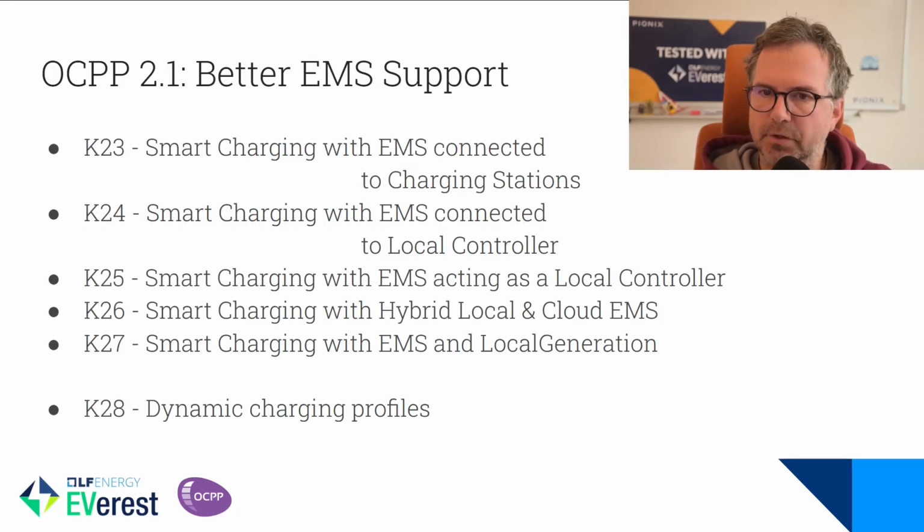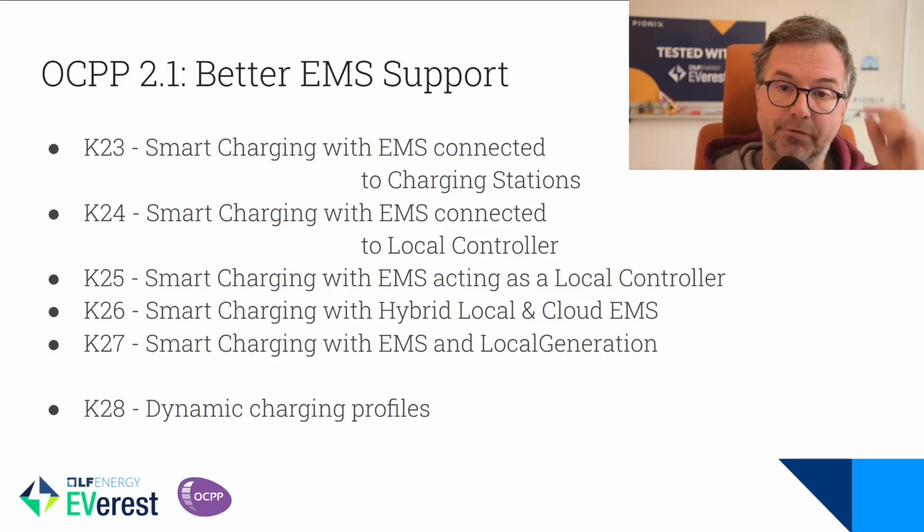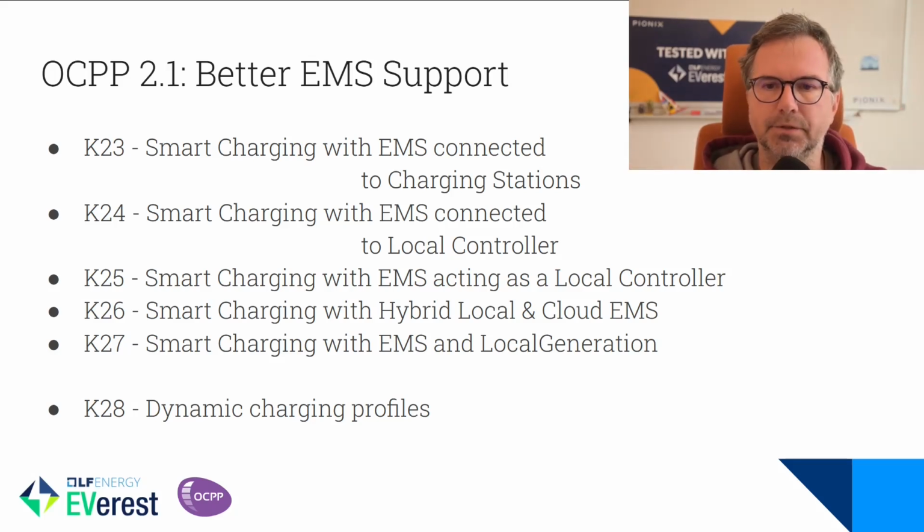Now, we've already touched a little bit on energy management systems. OCPP 2.1 already supports energy management systems. You can easily set up external constraints. So if there's an input coming in, if you have a CPMS doing something smart, you want to have some message going back telling the CPMS, hey, there is a local constraint. So somebody set a local limit based on grid constraints, based on available solar, that influences the charging speed.